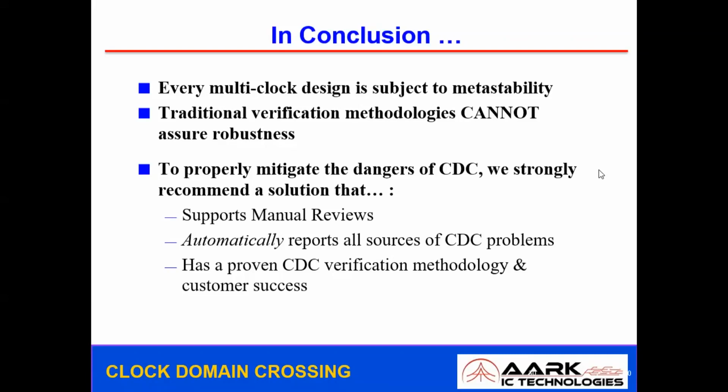Thank you, sir. Metastability can be avoided in a synchronous circuit with an additional clock. Is it affecting other parameters like power? The power might not be affected, but the frequency might be. We need to figure this out before we pass the final gate-level netlist: add the flops, and finally set the frequency. The frequency will be impacted because when we design a circuit, we add a two-stage synchronizer or reconvergence logic to avoid reconvergence errors. These are added on top of the functionality, and are not the functional blocks contributing to the actual specification. So when we add these, definitely there will be an impact on the frequency.